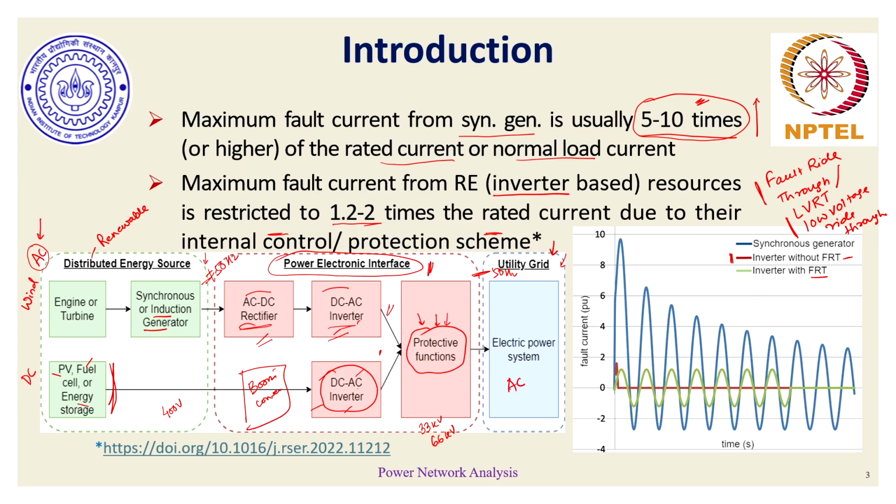So basically, it is all about sustaining the fault, during the fault, by a typical synchronous generator or renewable based resources. The blue line shows the synchronous generator phenomenon, which we have very well understood in the previous few lectures, and the red line, the response of the inverter, is an undesirable response, because if all inverters start not responding to the fault conditions and stop reciprocating, then unnecessarily some healthy load of the network will get isolated, and that may create trouble.